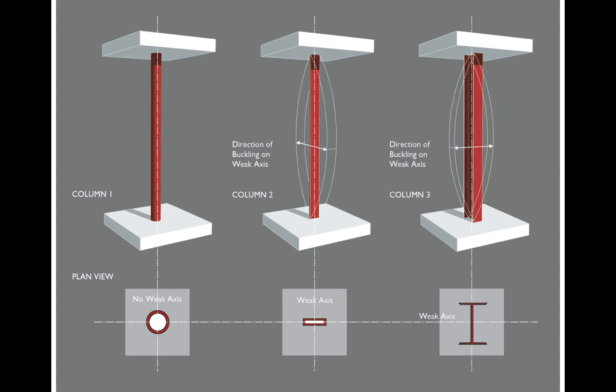Here you can see the problem of buckling. When we have a column that is sort of skinny and flat, we are worried not so much about the column taking the compressive load itself. We're worried about the column going into bending and basically buckling, getting out of the way of the load and leading the thing to collapse.